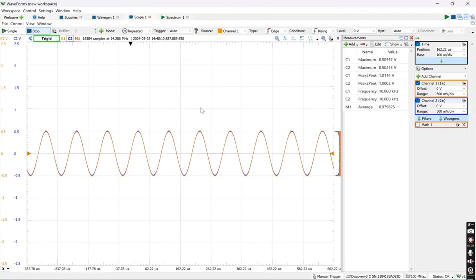However, here we run this and we will get an average gain with the C2 and C1 values. So here in this run, the average gain was calculated to be 0.98, which is above the minimum gain of 0.9, which is mentioned in the project specifications, and it also aligns with the gain that was found in LTSpice.